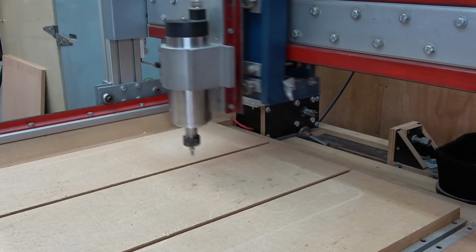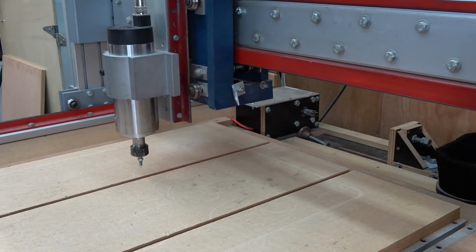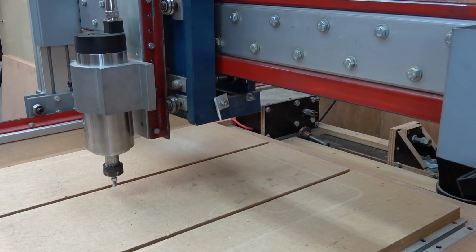So now we're going to run the exact same file in Mach 3 using exact stop. Mach 3 is set up with exactly the same parameters as my Masso, so we would expect to get the same results. If you have young children with you watching, I recommend they avert their eyes now. As you can see here, the motion is completely different. The machine moves and stops with each G-code instruction.